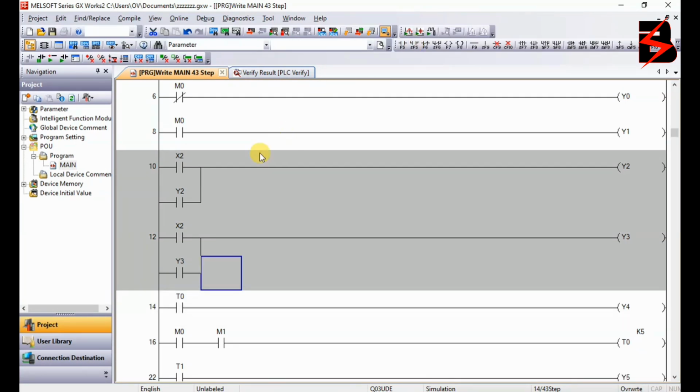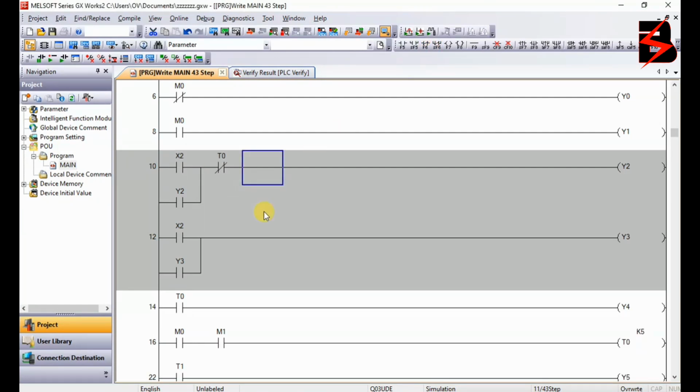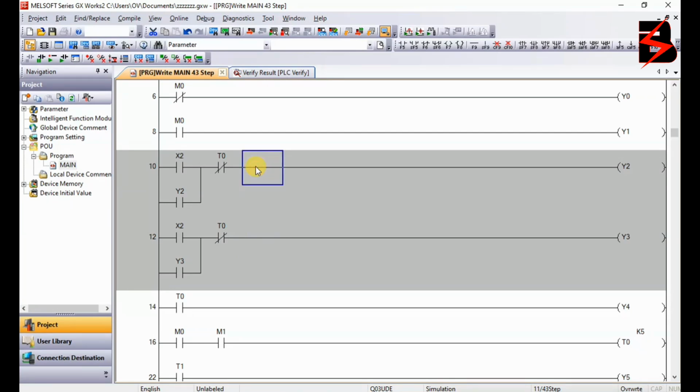Since they are self-holding, remember this timer 0 here, timer 0 is switching on Y4, that is the clamping. So when those leads and the bases are clamping, these conveyors have to stop and wait for the clamping. So that means this timer 0 also has to switch off these conveyors. Oh, so logical. Timer 0. Now also our emergency and the stop buttons also have to switch them off.